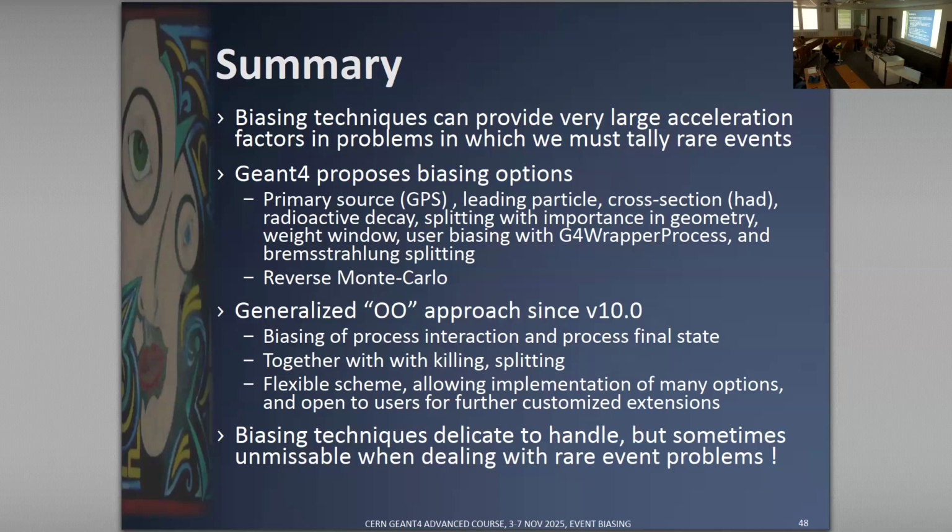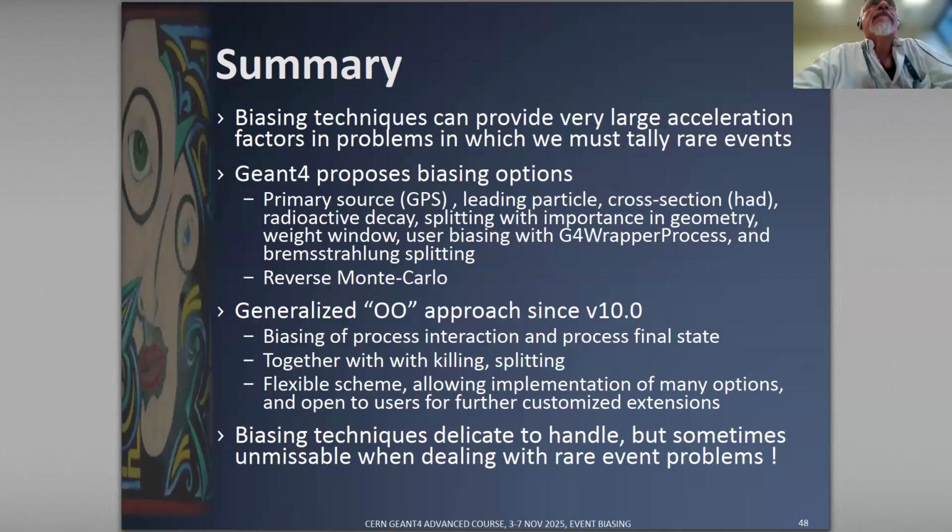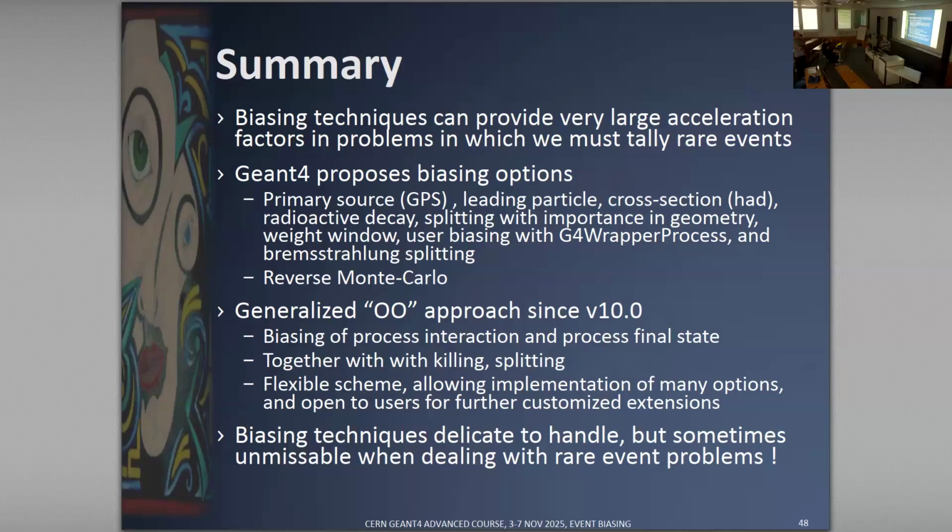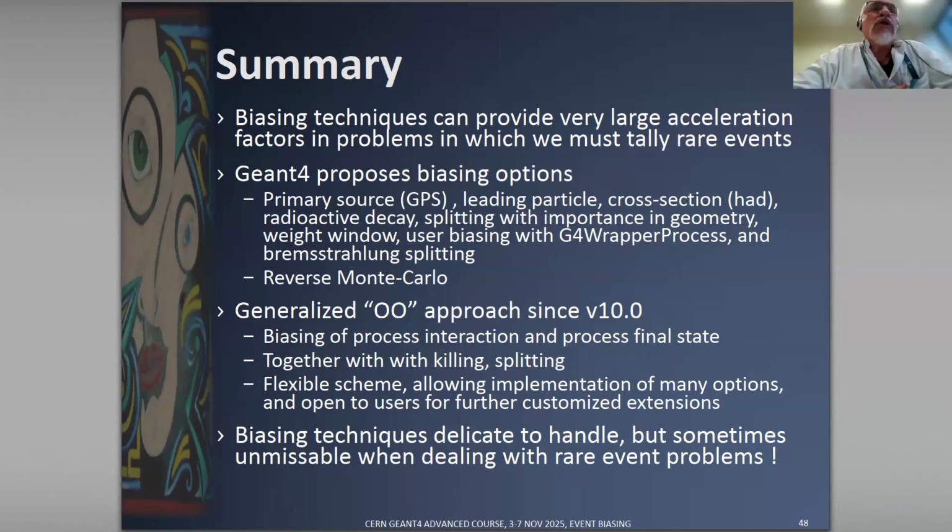There are a couple of questions from the room, but they're anonymous, so maybe I'll read them out. Regarding the thickness of the artificial splitting slice on page 9, do you have any recommendations for the starting point? For instance, should it be x times the mean free path, or the cut limits of a specific particle? Yes, it should typically be around the mean free path.